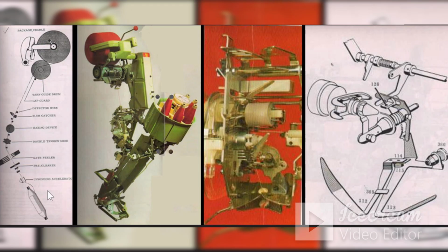So if the yarn breaks here, then you have no option but to change the entire ring frame bobbin. Therefore, occasionally you will find some ring frame bobbins which are ejected from the spindle, which are non-emptied, but they will be ejected when breakage takes place below the gate filler.